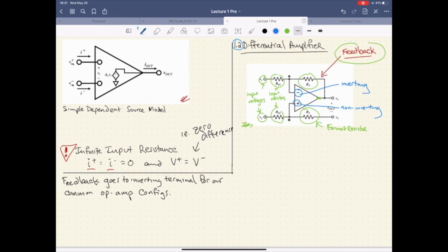Okay, so now that we kind of have all these parts figured out, oh, and one other thing, sorry, feed forward lead. That's right here. Okay. So for this particular problem, we're going to be measuring Vout as the difference between V3 and V4. Okay, it's measuring that voltage potential. In order to do this, we're going to use an old favorite, KCL. Right? Our good old current law. And we're going to do that at our two nodes, A and B.